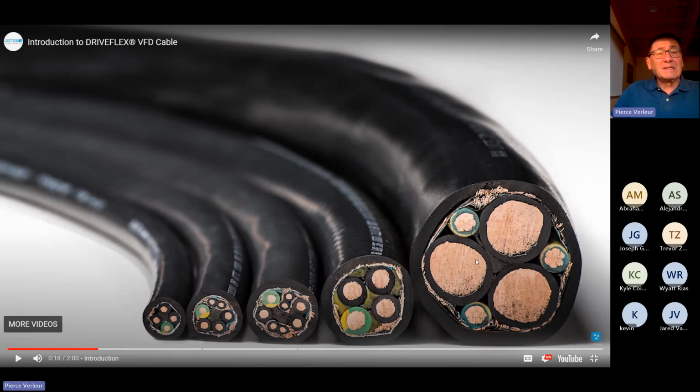But now you're putting a VFD in here instead of a contactor, and that changes the waveform going down the cable. So is it not logical to think that we might want to alter the cable characteristics so that we can ameliorate some of the effects of the new waveform? The new waveform is pulse width modulation, as you all know. That's how we generate the desired effect on the motor winding using a variable frequency drive.